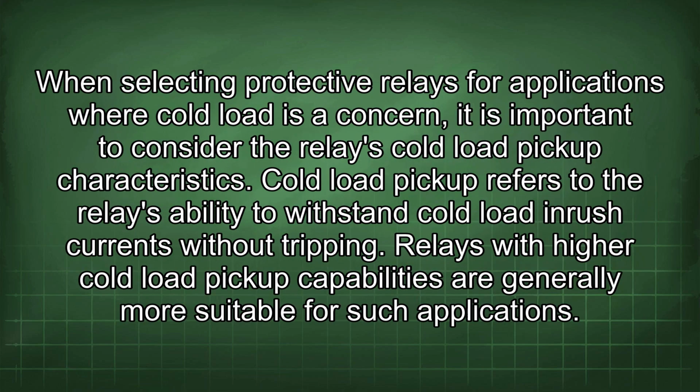When selecting protective relays for applications where cold load is a concern, it is important to consider the relay's cold load pickup characteristics. Cold load pickup refers to the relay's ability to withstand cold load inrush currents without tripping. Relays with high cold load pickup capabilities are generally more suitable for such applications.